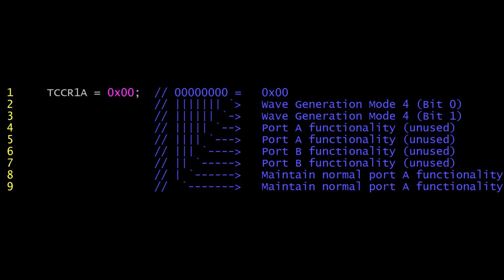I use the timer 1 timer to configure a periodic interrupt every 1 second. This requires configuring the timer through a few registers, the first of which is TCCR1A. Although this register is basically left alone, I used port A on this timer, so I had to ensure that it was enabled by setting the high 2 bits to 0.